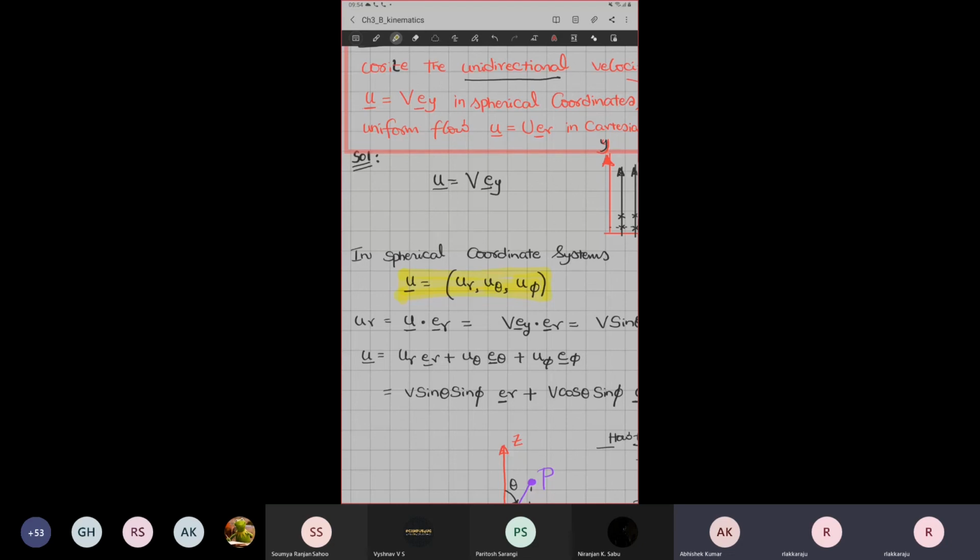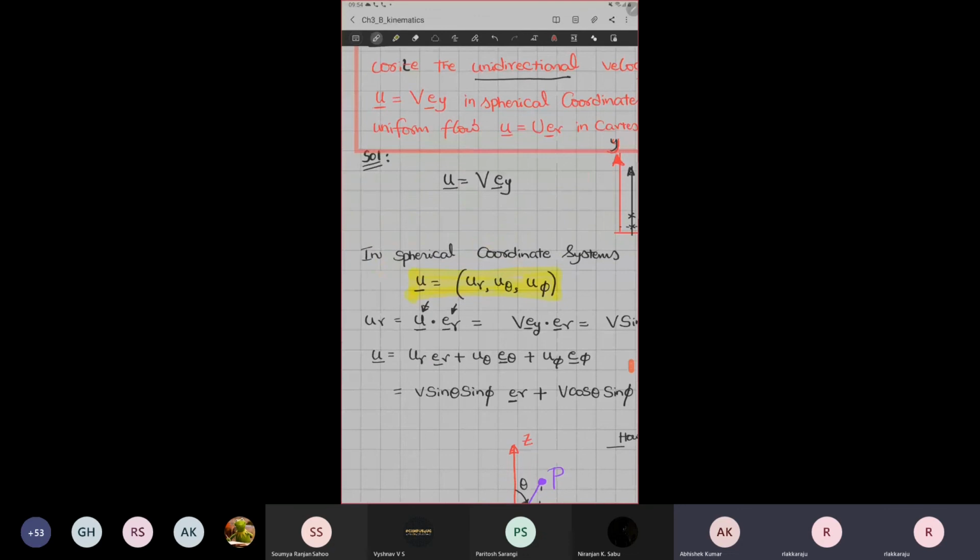Now, if I would like to have something like radial coordinates, what I have to do is pick any of your U velocity vector, dot with the particular radial vector, and you will get the Ur component. That means your U in Cartesian is your U, V, W. That means U multiplied by ex plus V multiplied by ey plus W multiplied by ez.